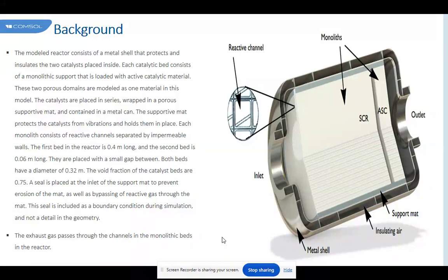However, the same volume percentage of washcoat was given to both monoliths and hence the same amount of catalyst, so the latter was discarded as a possible explanation of the differences. Regarding the temperature, CO in the feed is fairly diluted, so the heat released from the chemical reaction didn't drive significant changes in the temperature field.